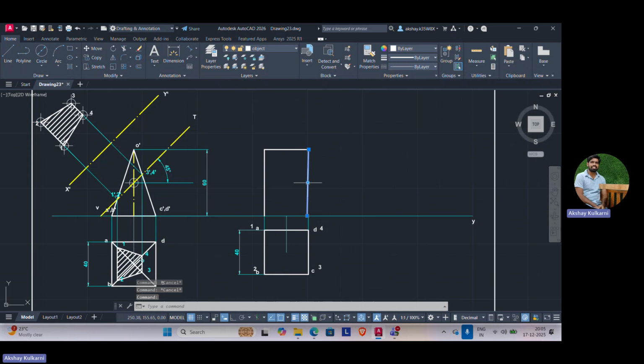It is not exactly joining because we have to turn on the ortho mode at the bottom. 60, enter, and bottom surface 40, enter. Join the axis line also. Okay, after joining, change this to axis. Select the center line, go for the layer, change it to dotted. Not dotted, it is axis. Axis line, and escape.